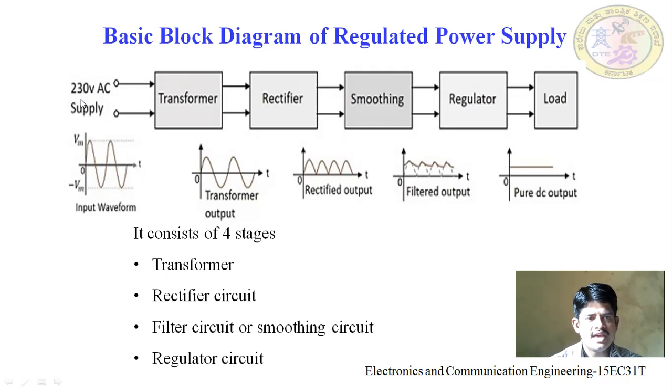Now, can we directly convert this into our required DC voltage? Normally, what DC voltage will we use for our instruments? Very little. We are not going to use 230 volt. We'll be using hardly 5 volt, 10 volt, 15 volt, very much lower than 230 volt. So what is the first step in moving from AC to DC? We have a large AC voltage, 230, but our requirement is very small, in the range of 5, 10, 15 volts. So first there is an imbalance in the amount of voltage between input and output. We need to step it down, that means reduce its size. How can we do it? We already learned: using the transformer.